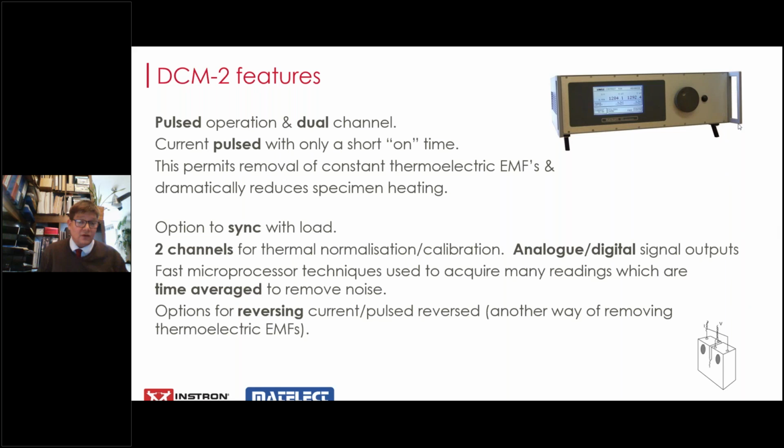So we know that once a crack has grown in your specimen, as you would need to do to grow your pre-crack or to get a da/dN curve, your specimen is opening and closing, at which point there is a possibility that the two freshly broken surfaces will come into contact and electrical current will be able to flow through them, rather than having to take the long path around the main bulk, and therefore you could get a change in your reading due to the crack being closed.